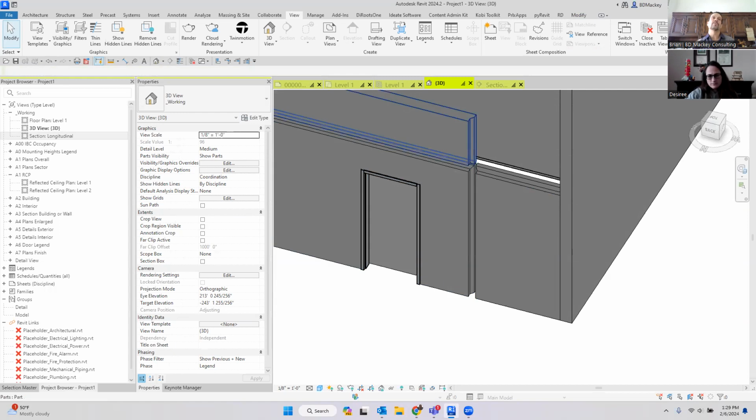The other thing that's going to be bizarre on that when you start getting into it is since you've converted a floor to a part, the floor will disappear. Excuse me, the floor will remain, but the part will disappear because the part is now outside of your view range, because floors have exceptions to the view range. They can be seen below the view range, parts cannot. So you'd be like, cool, now I've got to go change my view range to look down 6 inches or a foot or whatever you want to do.